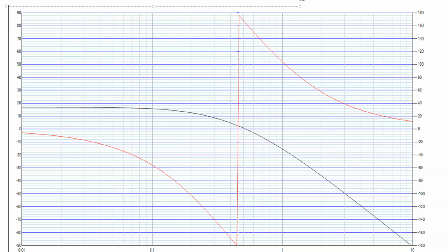We have here only the process Bode plot, so we have to add the controller gain and the controller phase to get the open loop magnitude and phase curve. So we have to add the gain of the controller to this curve. For this we need the gain in decibel.